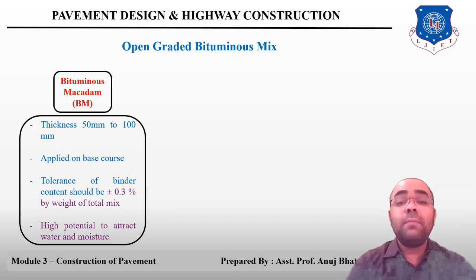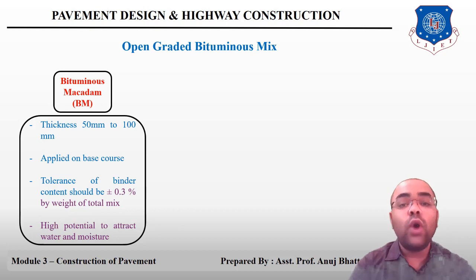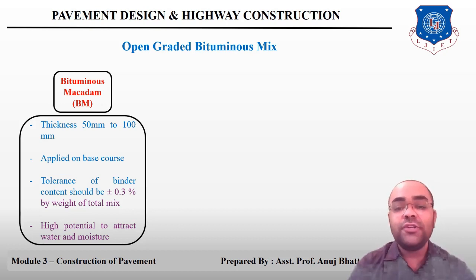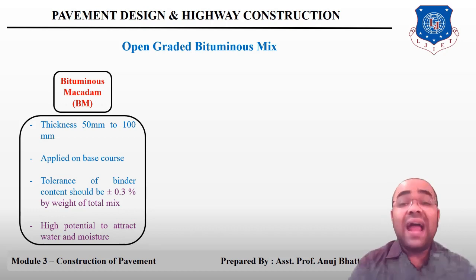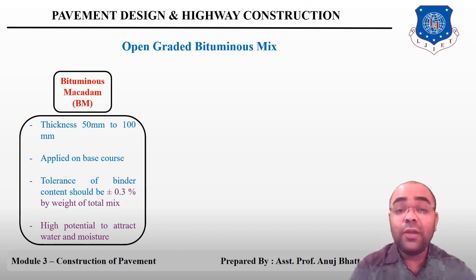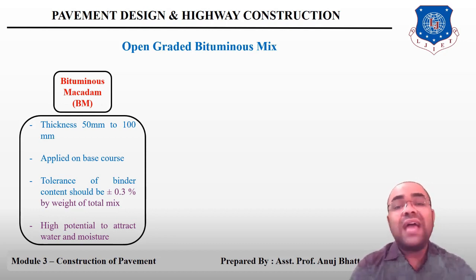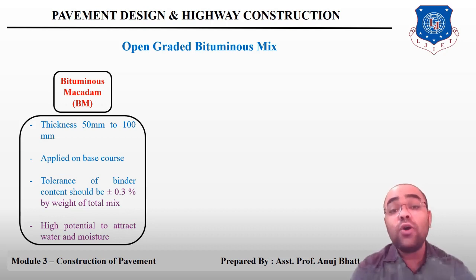The bituminous macadam has high potential to attract water and moisture within the pavement system, and that's why the adjacent layer of the pavement, which we can consider as the shoulder, should have proper drainage quality to prevent that moisture or water induced damage to the bituminous macadam.